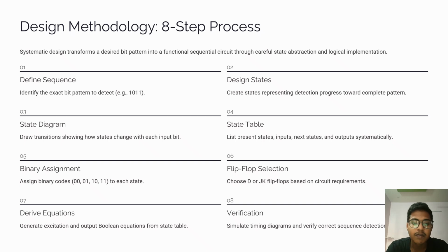From the diagram, we can convert the information to a state table. And step 5 is assign binary codes to the states. We know that binary is the basic language, and it has codes made of 1s and 0s. It is easy to assign codes to the states.